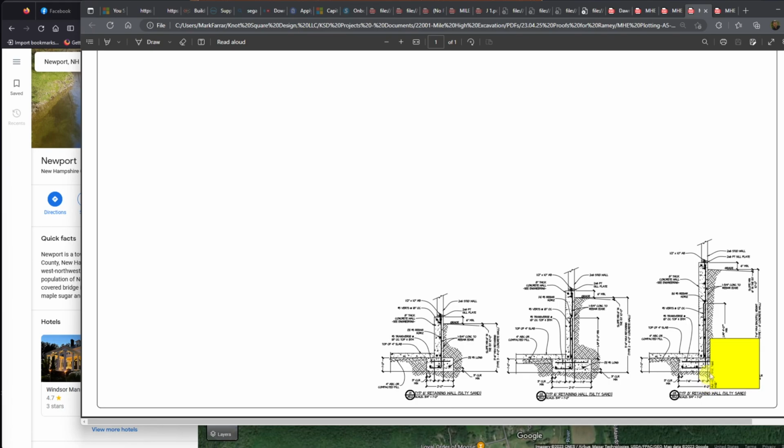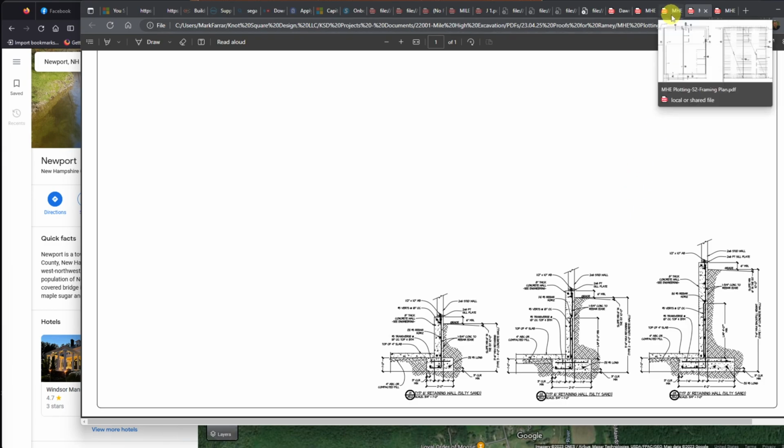And so they have different rebar. They have different footing widths for the different heights and different values of dirt that we're holding back. This is a particular situation where I've got a slab on grade on the other side. Everything's different. So when I get into retaining walls that are not within the prescriptive code, I need to get the stamp from Dimitri on those walls. I drew all of this, so I draw it up for him, and then he stamps it.